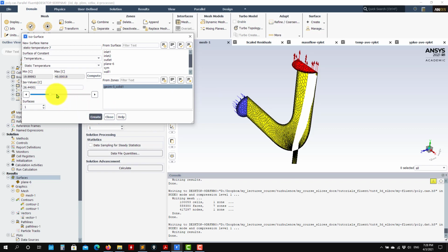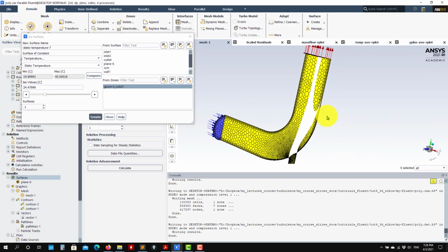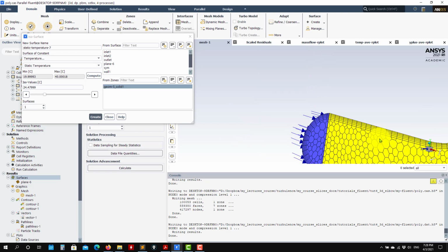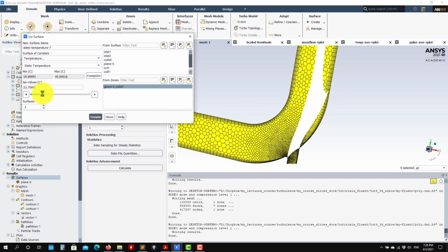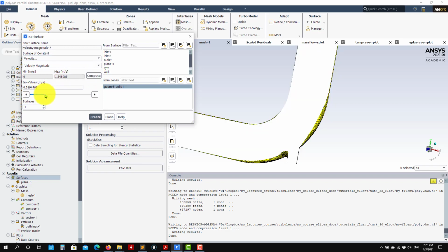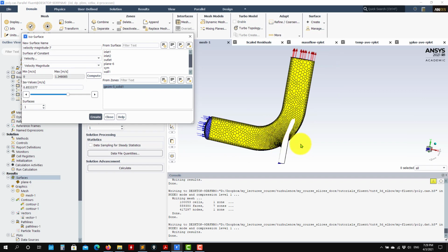So see here how the influence. So this is isosurfaces. It's useful for post-processing, sure, but also for selecting the cells where you want to apply that mesh refinement, okay? So see here that, let me move here, different values, so you can also use it with different quantities. So velocity, for instance, the regions where I have the largest velocity. Or you can go, let me go Y velocity, Y component, compute, and I want negative regions.